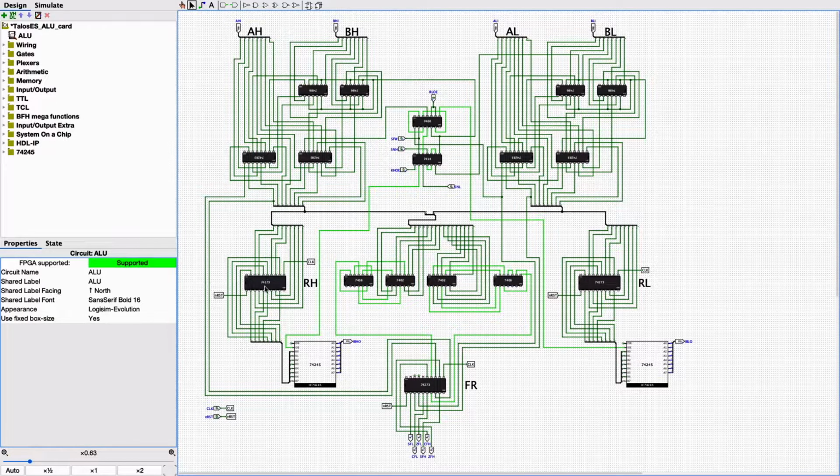And the same thing for the other side: zero flag, carry flag, and the sign flag. And that allows you to have conditional branches based on whether the operation has produced a zero flag or a sign flag or a carry flag, and you branch or not branch depending on that. So these 2 bits compute whether it's 0 for the low part, and these 2 bits compute whether it's 0 for the high part, and the carry and sign are just bits that are directly available from the ALUs. This is a carry out, this is another carry out, or just the most significant bit. This is the sign bit high, and this is the sign bit low. That's all there is to it.